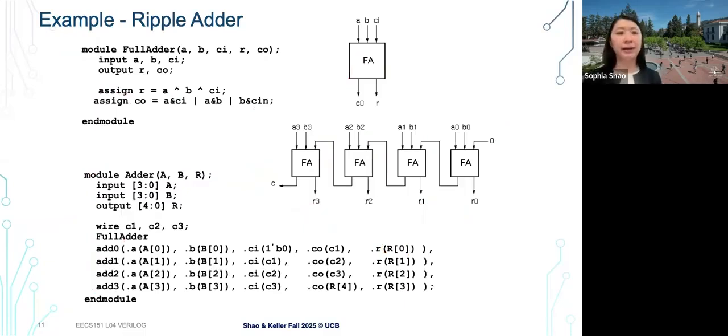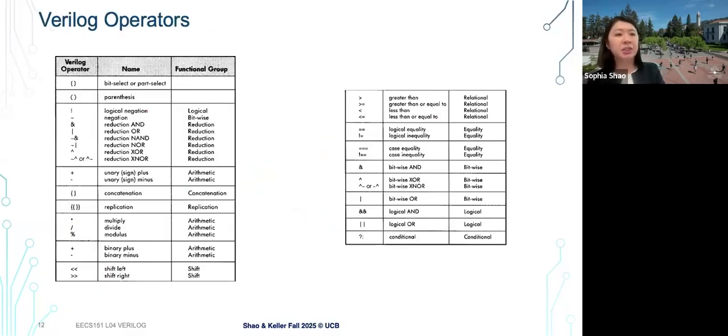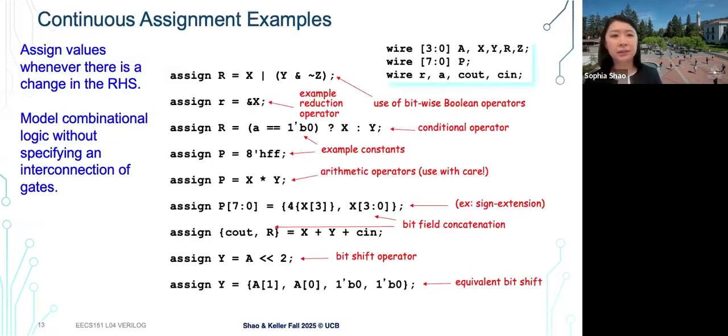I guess for more complex combinational logic, we mentioned you can use this kind of more powerful operator directly instead of using structural Verilog to build things from the ground up. And here is a list of commonly used operators that have pretty wide coverage of different components. We'll not go through them one by one, but with those different operators, you can do a lot of the combinational circuit design through this assign statement to describe your hardware.